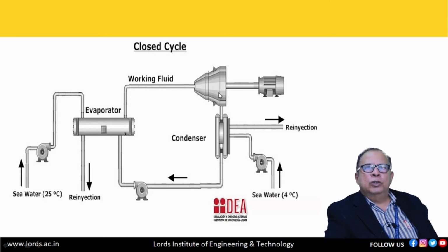Then the exhausted ammonia will be transferred to the condenser. As I told you, the condenser is a heat exchanger. Here in this condenser, seawater at 4 degrees centigrade is supplied, passing through the condenser. Because of that temperature, the ammonia will be condensed. That means liquid ammonia is formed.